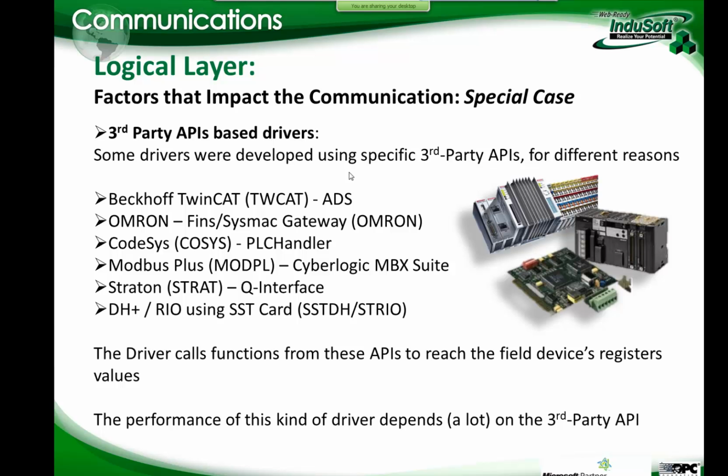So when I ask for the value of one variable, they will not go to the PLC and bring this variable. No, they already have the value, and they're going to send it to me. Okay? When you talk about the SST DH+ card, it's not exactly like that. We're going to send a message, the card is going to go to the PLC and bring the information for us. But again, that's an older protocol, and that was the best that could be done back in time.